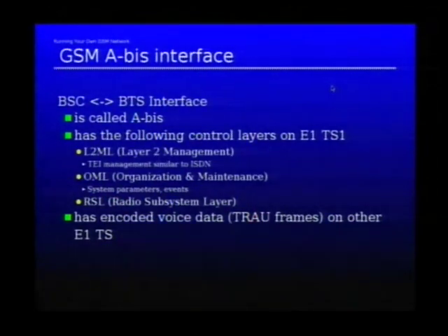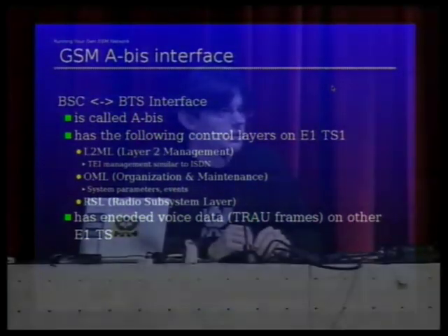It's layer 2 management, which is for TEI establishment. If somebody has dealt with ISDN before, you know TEIs. Then the organization maintenance layer and the radio subsystem layer. Basically you have one time slot on the E1 which has the actual control channel, and the other time slots then have speech data. I'm going to go a little bit more into detail.